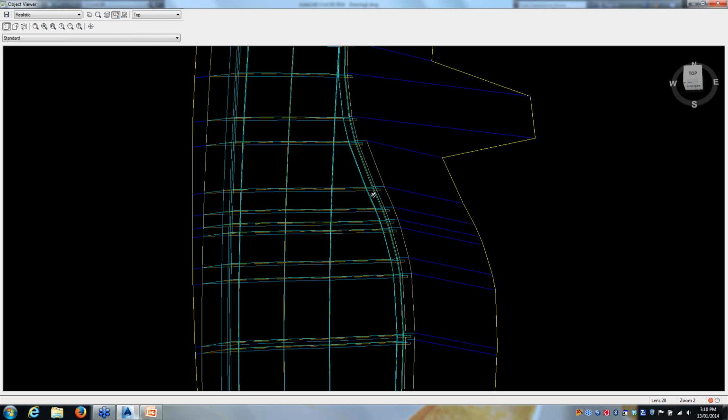Now you may want to close up the transverse lines on this corridor, those where the cross-sectional shape is applied, and they're called the frequency lines, or the frequency of the corridor. So we can actually increase the frequency to make those curves sample a little bit better.